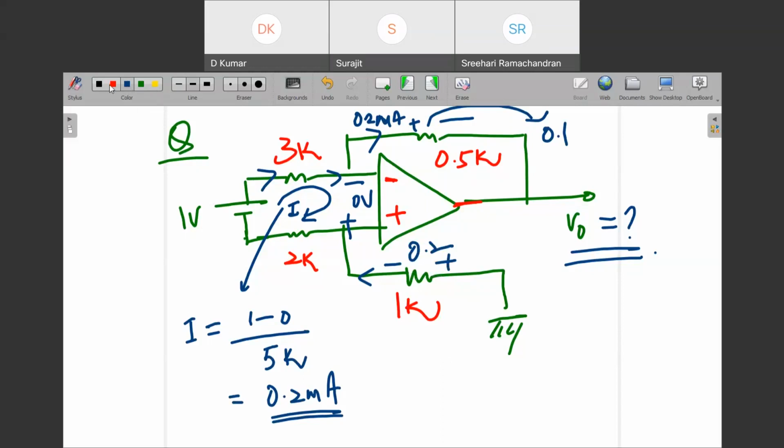See, so I'm going like this. If it's a blunder, I'm really sorry. If I take the lower as -1, and then move through like this, 2K and 1K as a voltage divider, in getting that point, the positive input terminal voltage as -1/2, and apply virtual ground and use the same -1/2 as the voltage of the negative terminal. So how much are you getting as the answer then?